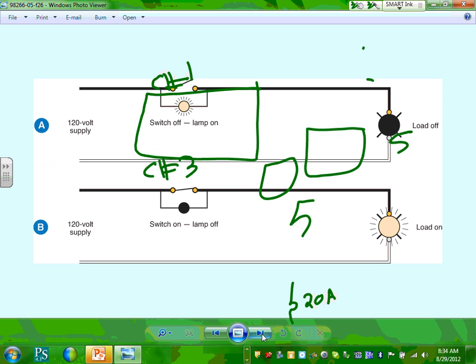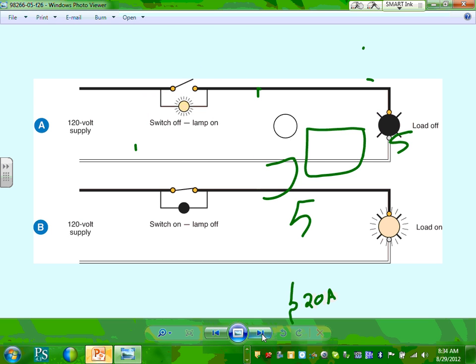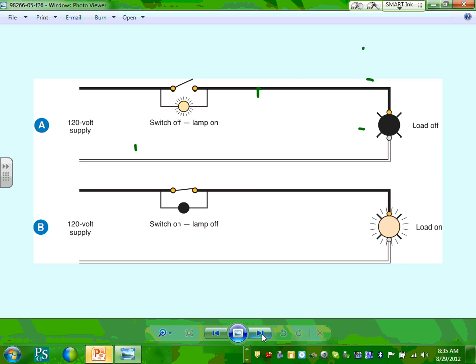Talked about this. Okay, a couple of things, guys, pilot devices and so forth, if you don't mind me just touching on these. I don't know if you have wired a switch where the switch knob actually has a light in it. There are two ways you can do it. This one, it's cool, is on, indicating light. This one is on when the load is off. Anybody wired any of these? That's inside the switch itself.